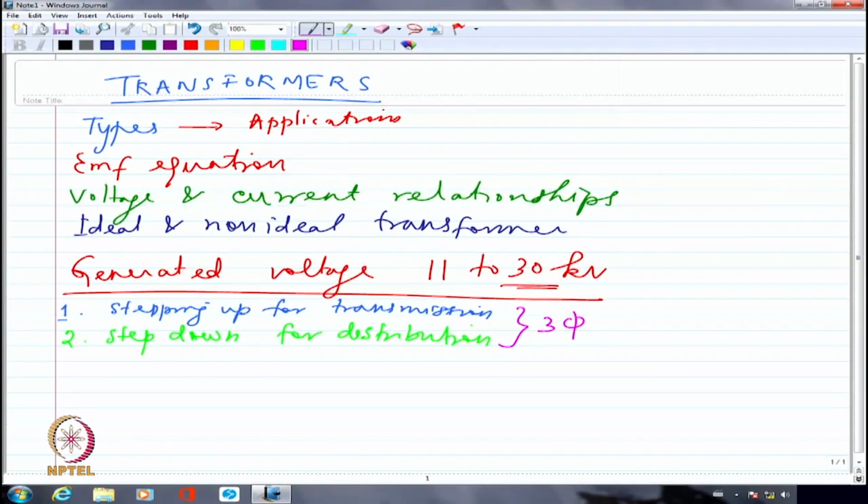Right? This particular railway electrification is done with the help of single phase AC, because the return route is not there at all. Return conductor is not there at all. The rail serves as the return conductor. There will be generally a line which is the overhead transmission line, somewhat like this. And you would see that a U-shaped conductor will be touching from the train.